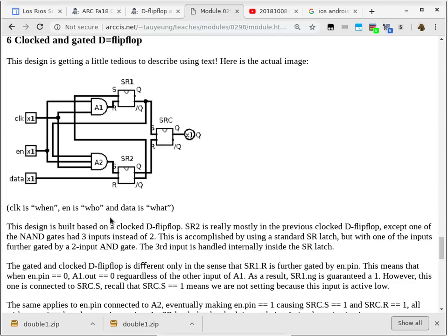Is that okay? Yep. So the enable was member or non-member, right, in this case? Mm-hmm. And then the clock is just... No, you have 2 devices now. One device is labeled member, the other device is labeled non-member. They have their clocks hooked up to exactly the same clicker, but the EN is separate. One EN goes to the foot paddle that says members, and the other goes to the foot paddle that says non-members. Okay? So this is the next design.